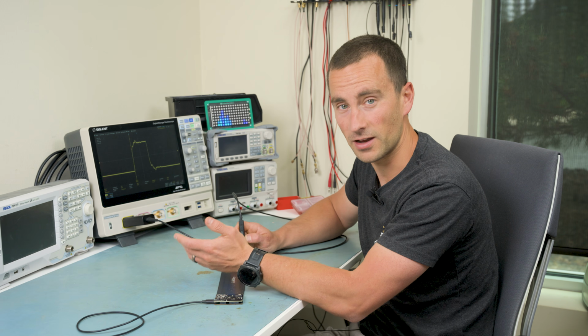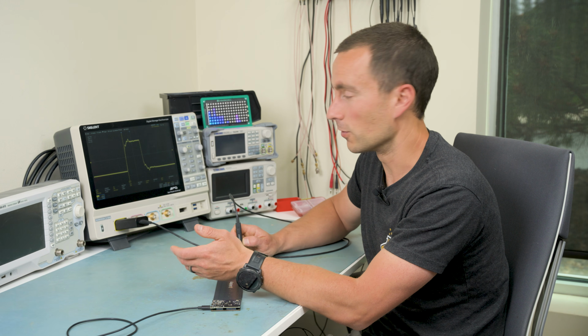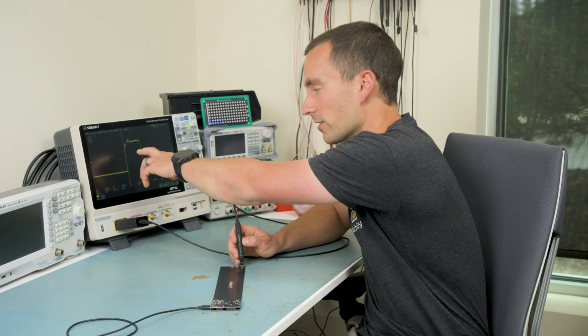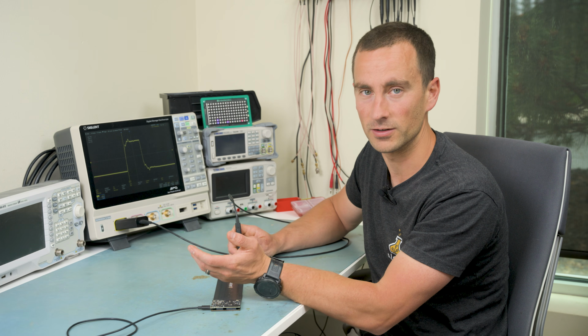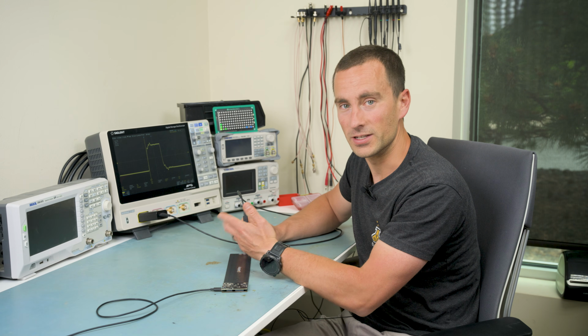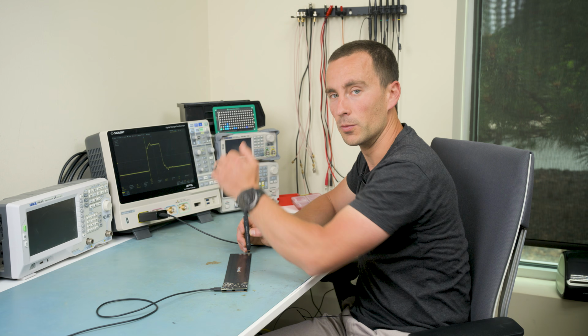The signal integrity of this is obviously pretty bad, and we're using 10 nanosecond pulses, which are fairly long. If you were running at like a gigahertz, the width of this pulse would only be a tenth of what it is here. This is the equivalent of like a 100 megahertz bus, and you can see how this could easily impact not only the signal you're sending, but even multiple bits later.